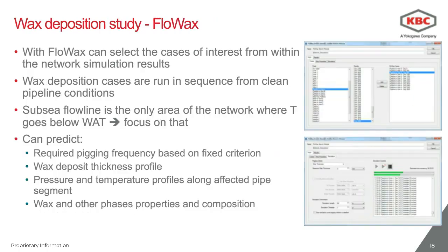So now I've got a better idea of what's going to happen during the life of the field. I can concentrate on the wax deposition study and see whether wax is indeed going to be a problem in these first 7 or 8 years of production, because I know that in the late part of the life of the field, it's not going to be a problem for sure.